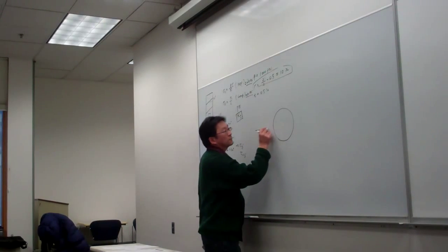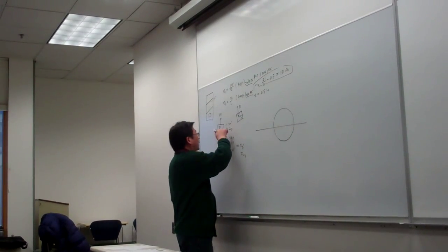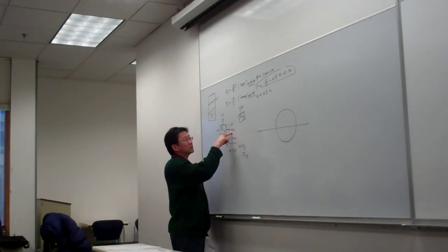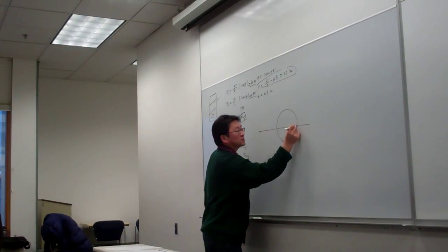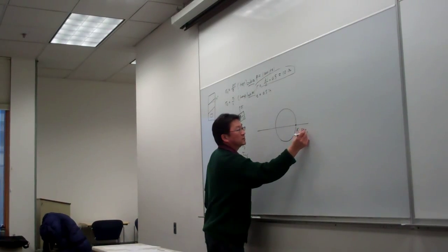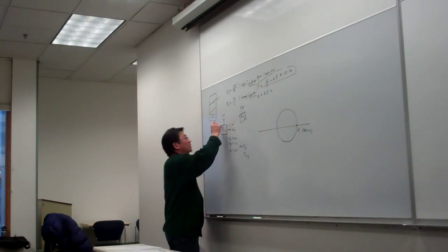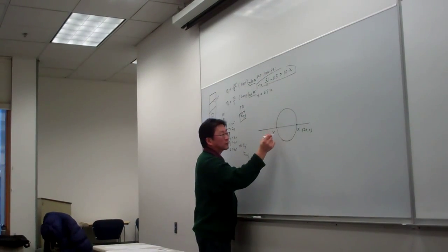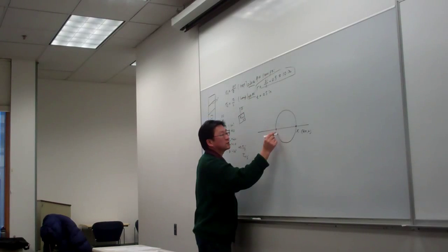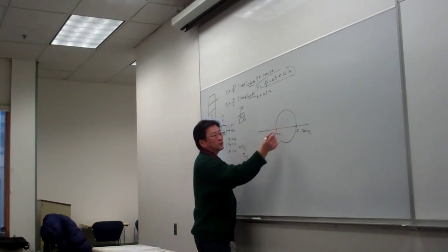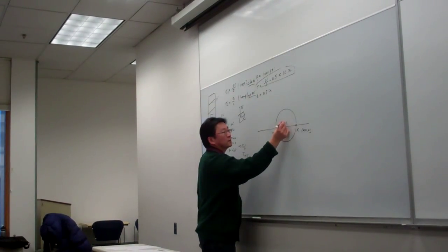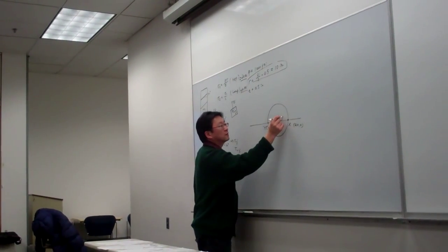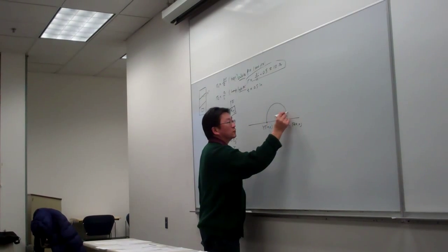For the Mohr circle, here we allocate the points. Here is the X point, which has the coordinate 20, 0. And here is the Y point, so that is 10, 0. So this is the Y plane, and that is 10, 0. So for this Mohr circle, it's centered at 15, and it has the radius equal to 5.